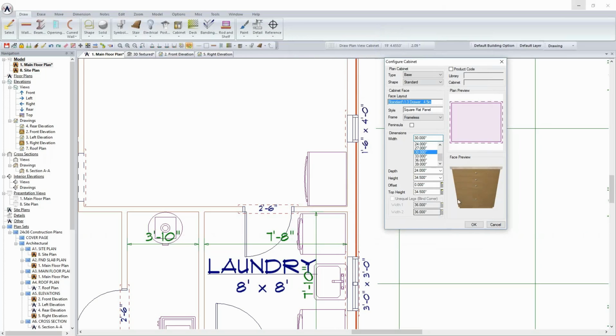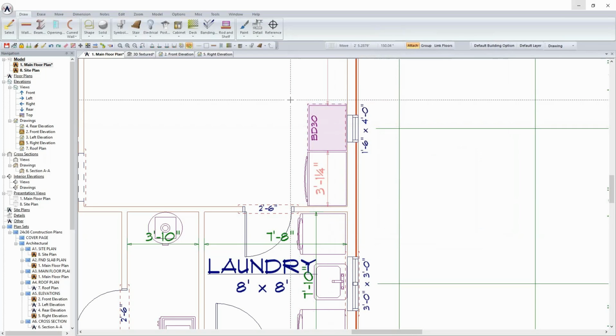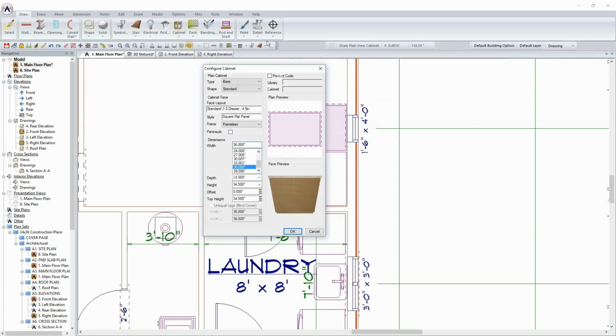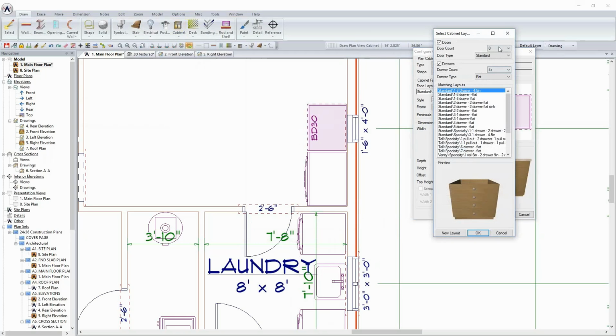And so when I do this and I click OK, it gives me the cabinet that's there, and I can now position my cursor where I want the cabinet to be drawn and even move it into place at this stage, because I'm just simply running the design. And so from this point forward, using the base cabinets as my start point, I can pick the different styles once again. And so I'm just modifying this on the fly as we go, and I can even pick from the predefined settings that are down here, okay, depending on what it is I'm trying to do with my cabinets. So I'm just going to go with a standard two-door cabinet at this stage,